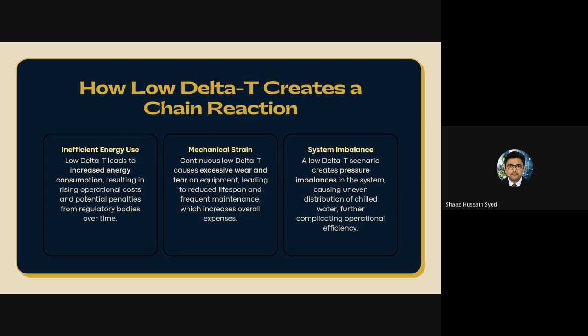What will the district cooling supplier's management see? Low return temperature, high flow, and low delta T. That's how they will issue you the penalties.